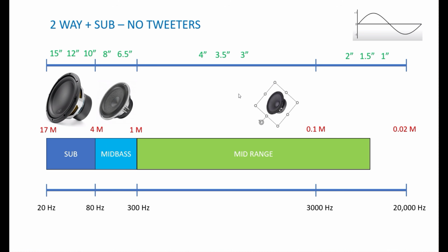So widebands are normally, they won't be 4-inch. They're probably 3-inch or maybe even 2.5-inch, and they're a compromise, right, between a tweeter and a mid to try to get a mid-range to play super high. But once again, you can have a decent system with it. You just be aware that the top end is going to suffer, right? Okay, so they're just like some of the common systems that people might be running.